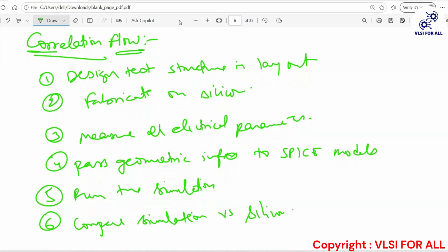There is one question. In this tool, we run fabrications in silicon step. See, fabrication is not something we run, right? Fabrication is when we get the final step like the GDS2 file, we give that to the foundry, and the foundry will create that into the chip. So that is the fabrication. Fabrication we don't run and we can't run, right? We do the simulations. We have the environment of simulation. We are exactly emulating the same characteristics of the device, right?